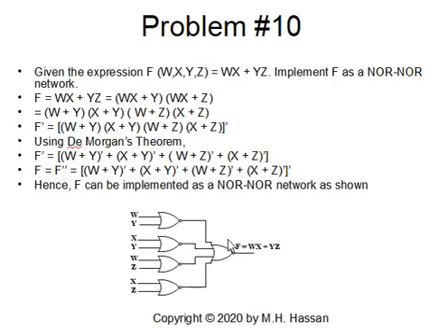To do that, we will replace WX or YZ with (W or Y)(X or Y)(W or Z)(X or Z), using the distributive law. And we take F prime, so we will complement all these.